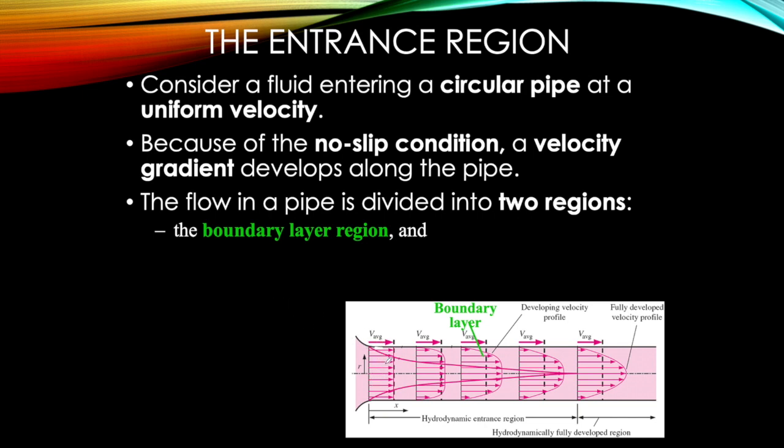So as the x increases, these effects that stick, okay, we know that the fluid layer sticks to the surface and will affect the adjacent layer. So it will increase as the x coordinate increases. So if we combine all those affected fluid layers, we will get a boundary layer region.